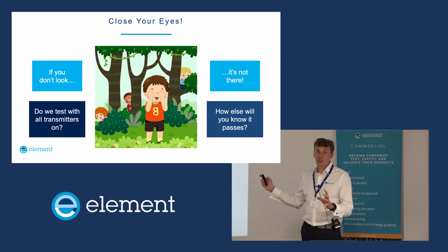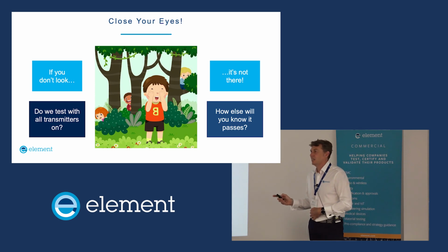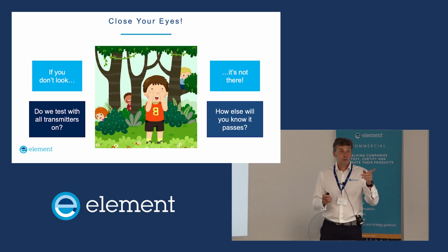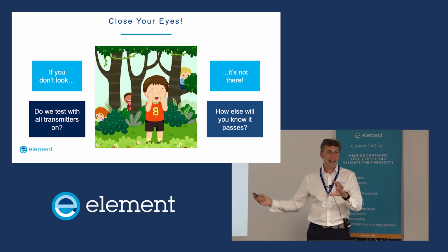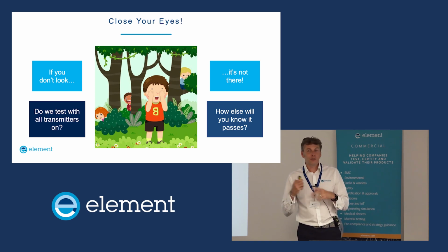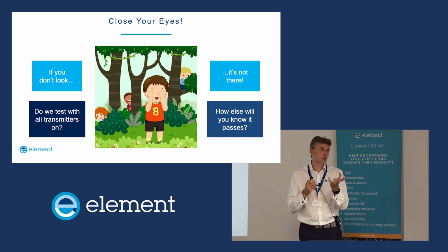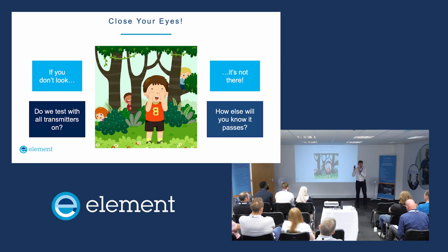This slide, I'm almost finished. This slide I threw in at the end where I was at a workshop recently, and they were talking about something Rob talked about, which was intermodulation products. Let's say you put LTE and Wi-Fi into a product. The rules are very much written around a radio. So you test the LTE, and then you test the Bluetooth. And the FCC rules do have a little statement that says if there's multiple radios in a product, you have to have them all on during the testing to make sure they don't interfere.